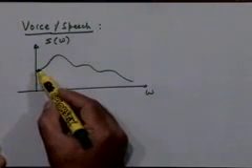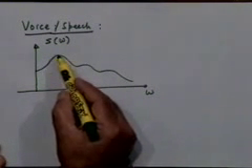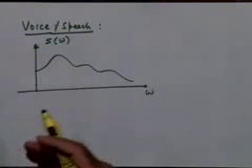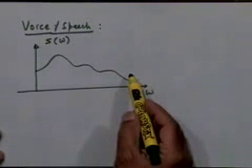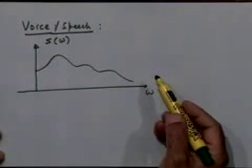Signal power as a function of frequency, and typically this is the tool that you employ when you're talking about random signals. And if you model speech as a random signal, it's not really all that random, although there is randomness in it. One can see that the power spectrum looks something like this, builds up from slightly lower energy at the lowest frequency end to peak energy at about a few hundred hertz, which will vary from speaker to speaker, and which will vary with the information that you are speaking. So this spectrum is not really fixed, right? This is just a typical plot that you might see.